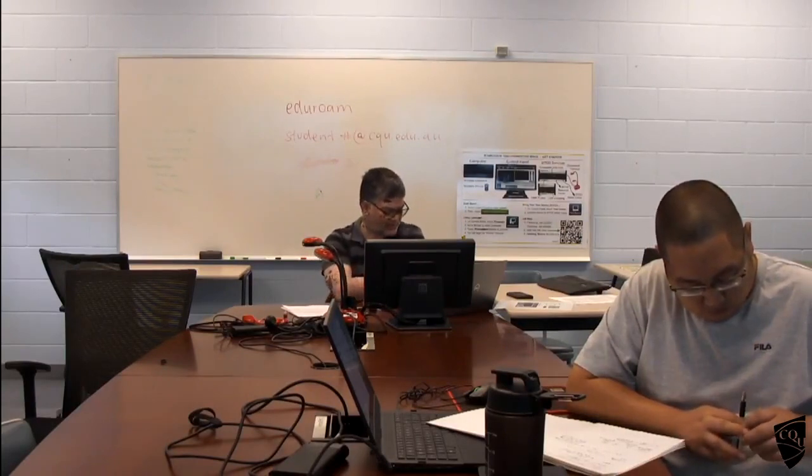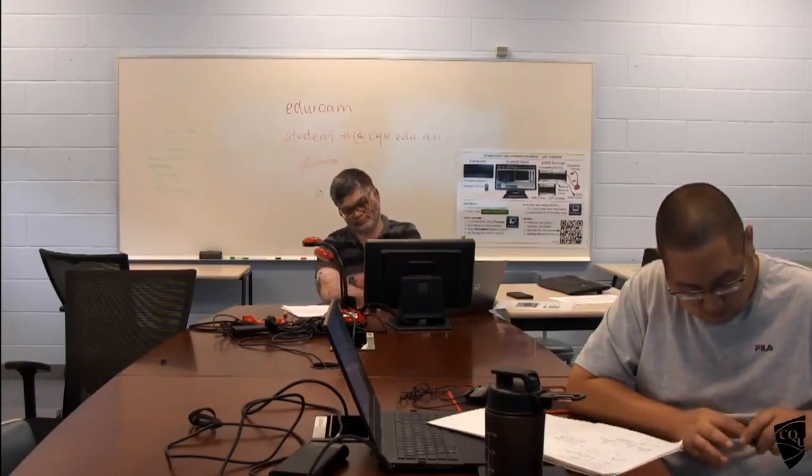Why do I need the neutral axis? Technically I found the centroid, and for elastic materials, the neutral axis will pass through the centroid. Why do I need this neutral axis or centroid? What is the purpose? When you do something, you should know why you are doing it. Because to find the deflection, I need the I value.